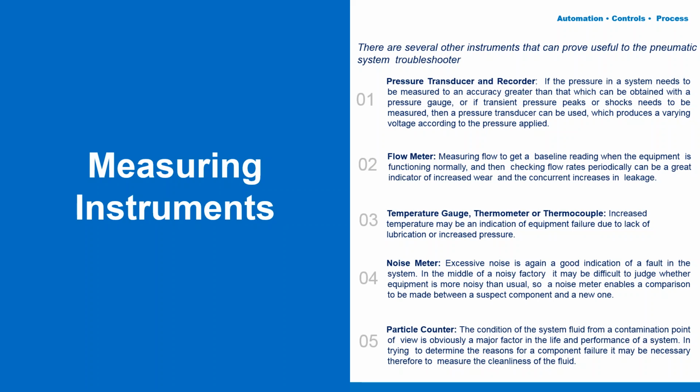And I'll mention here as an aside, I would hold that almost any pneumatic failure could be predicted by leakage. A cylinder that stops moving has got to have been leaking over the piston seals or the rod seals or both for a significant period of time before it actually quits. So leakage is a very good indicator of the health of a machine.